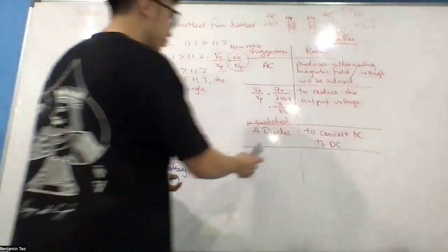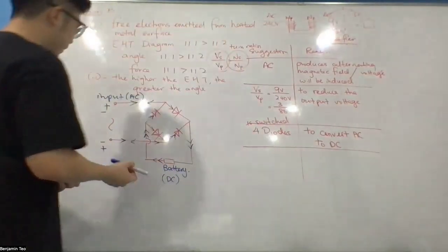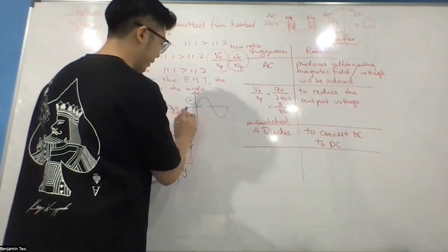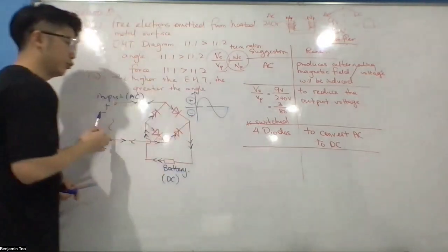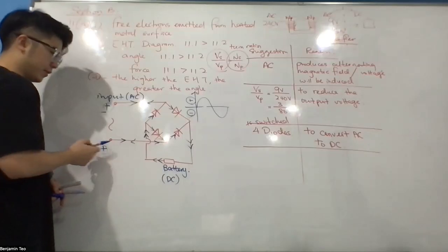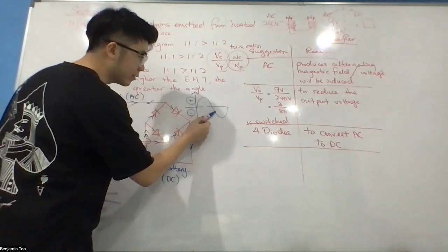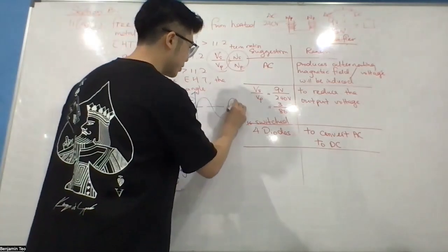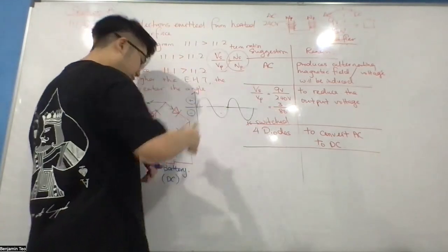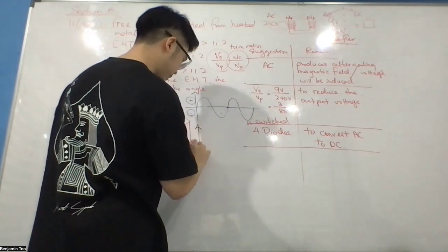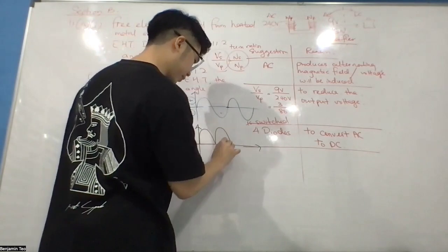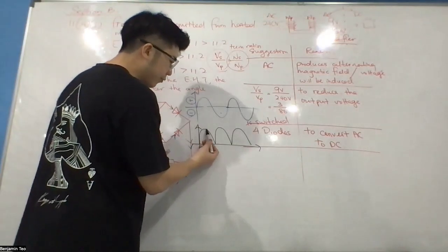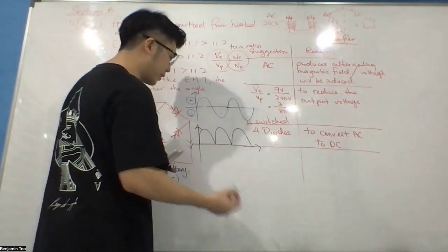Okay, then what else can we improve? When you convert AC to DC, the AC graph goes above and below, positive and negative, meaning it changes direction. First this half is positive, then the second half is reversed, so the graph goes into the negative region. After converting to DC, all the negative parts flip upwards, so the DC graph looks like this. But this current fluctuates, rise and fall, rise and fall. We don't want that to happen.